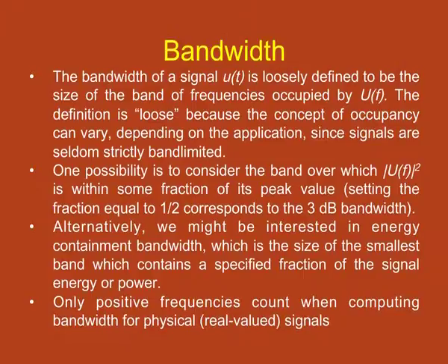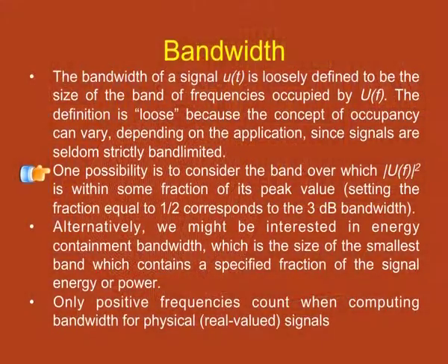So, all the practical signals which can be generated are going to be limited in time. So, no signal which you will encounter ever in your life is going to have limited range in frequencies. If it is not contained in a certain frequency range, then how are we going to introduce this concept of bandwidth? There are several criteria which can be put forward. One of the simplest criteria could be that you define the range of frequencies for which the signal energy goes within a certain fraction of the peak signal energy.